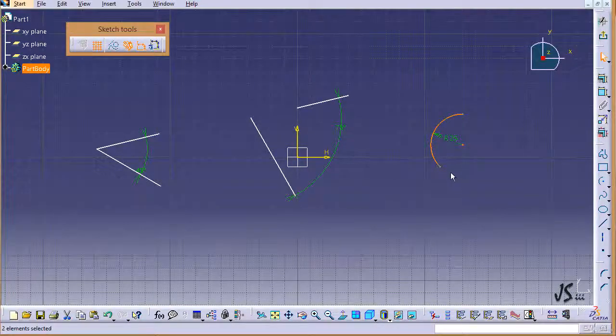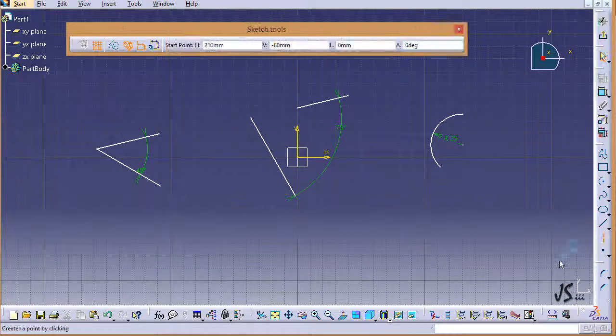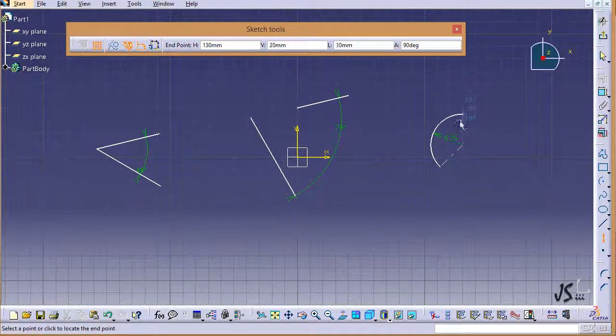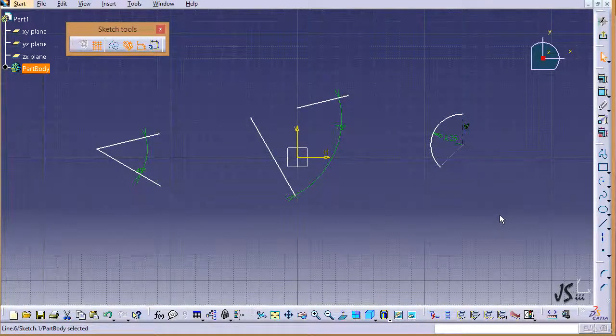So if I want to have an angle for an arc, I can have some tricks like drawing some construction lines. Like this one, for example, I select an axis, draw the axis from the center of the arc to here, and again I'm going to have another axis and draw it from here to here. Now I select the first axis, and the second one has a vertical constraint. Doesn't really matter, that's good.